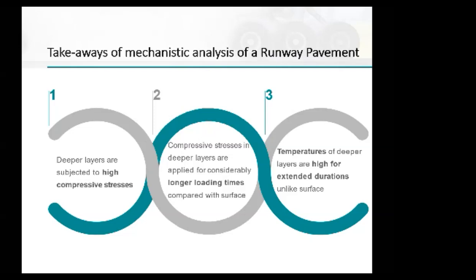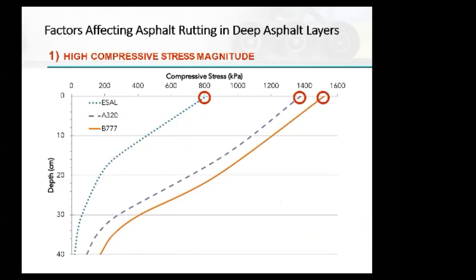And that's damaging, because we know the longer the loading time, the more creep strain you will have and you might get damage. The third thing is that temperatures of deeper layers are high for extended durations compared to the surface. So I have temperature to worry about as well. Deeper layers have high temperatures and they last for a long time, as you will see.